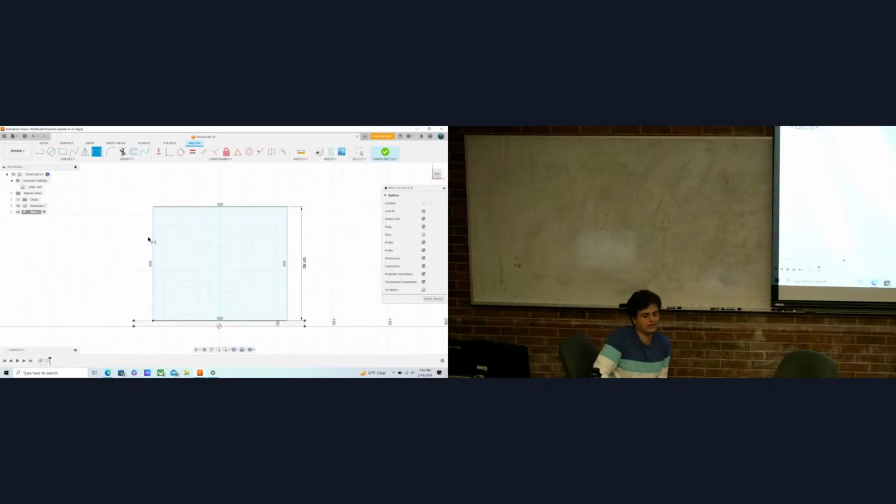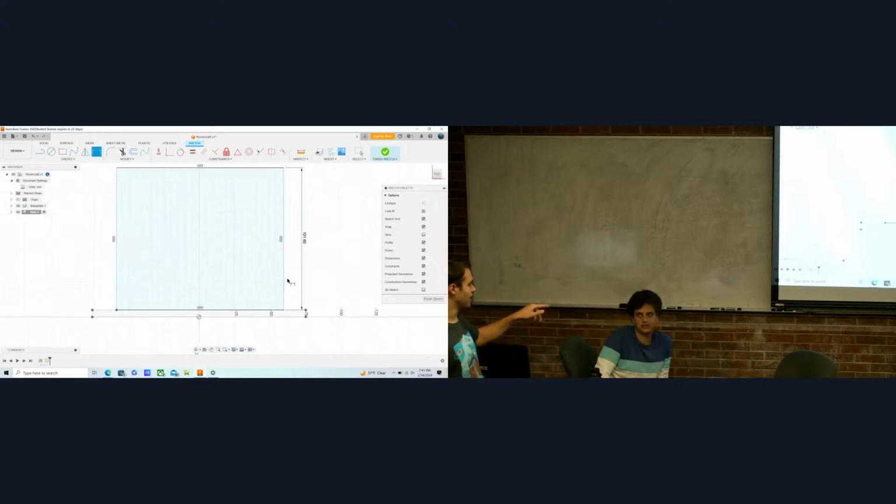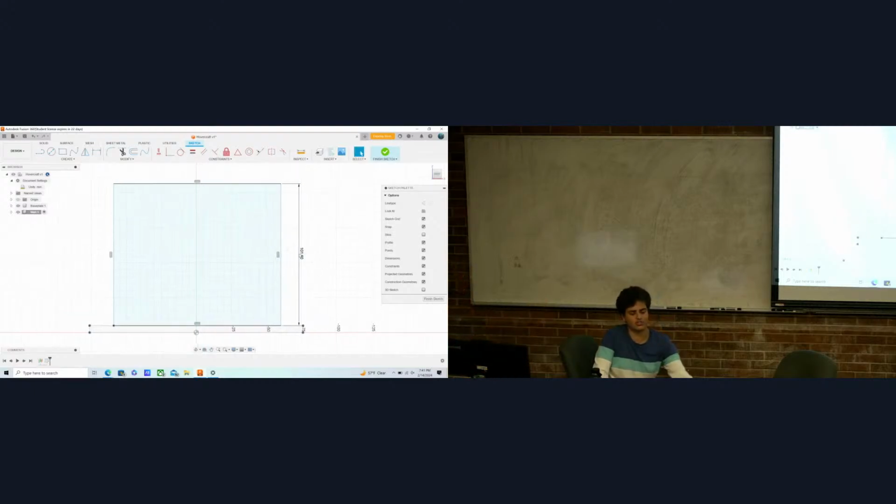And then we need to dimension the width. Before, like we've done, you could dimension the actual width of this. But instead, I'm going to dimension it. Oh, yeah. We just added a dimension on this line that is 4 inches tall. So you just hit sketch dimension with that edge, drag that out. You're good. Is everybody good here?